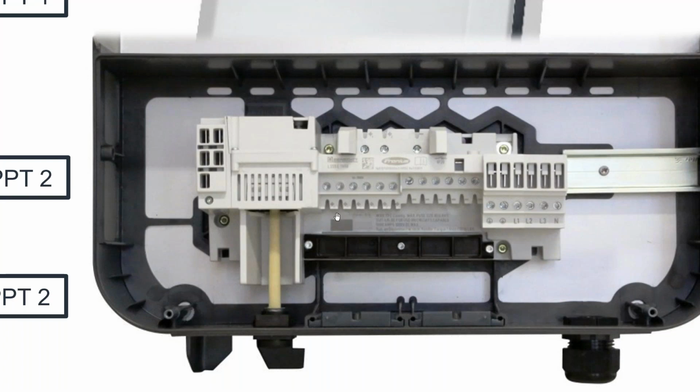The best practice would be to connect 2 strings, that is 1 string here, another string here. Then for MPPT2, you jump to the next MPPT, connect 1 here, and then another 1 here. And then their respective negative cables will come here respectively without any specific order.